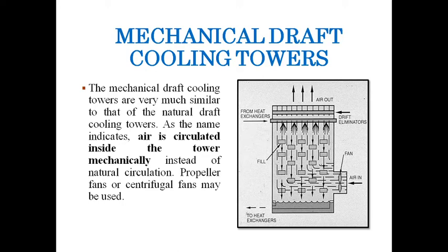So this entire process releases the hot air at the top of the tower, and the cooled water is sent to the heat exchanger. In this tower, fills are also used. What is the purpose of the fill here? Fill is the medium used in a cooling tower to increase the surface area. Increased surface area allows maximum contact between air and water, which allows a greater evaporation rate. This is the purpose of the fill.